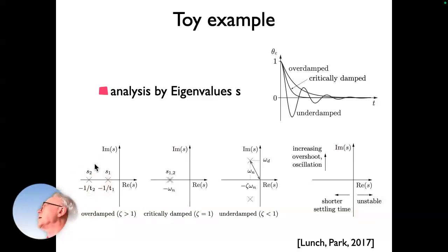The imaginary part reflects the frequency of the oscillations around the controlled state, and the real part is a measure of the damping. If you have a very negative real part, then you have a very short settling time. It's very rapid damping; it settles very quickly. If you have a positive eigenvalue, you're unstable. Remember that from our use of dynamics for motion planning, right?